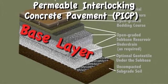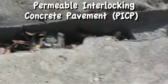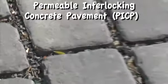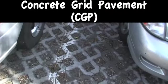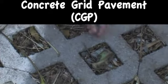Rather than sand, PICP generally uses 1/8 inch diameter stone to fill the spaces between the pavers. Additionally, because interlocking pavers are more difficult to install than freestanding pavers, an experienced contractor is recommended.